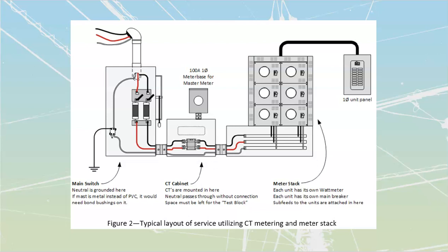Ahead of my main overcurrent device, I'm going to have a couple of conductors, these ones over here. These are going to be called the Consumer's Service Conductor. I'm just going to short form that as CSC. Consumer Service Conductors, because these are owned by the consumer and they are put in place by you as the electrical contractor. Over here, we're going to make a connection, and from here, the conductors that are going to be coming in are going to be known as my supply service.